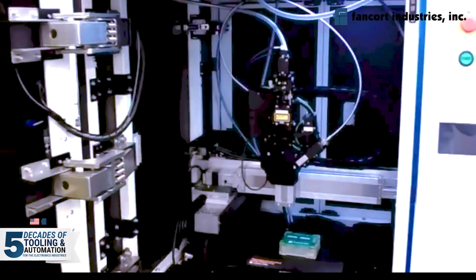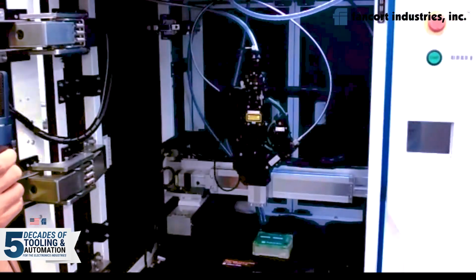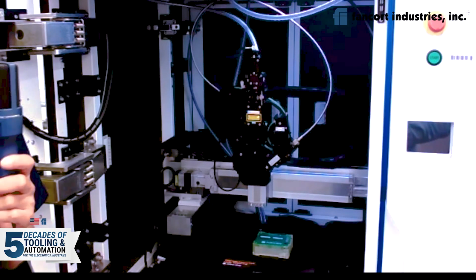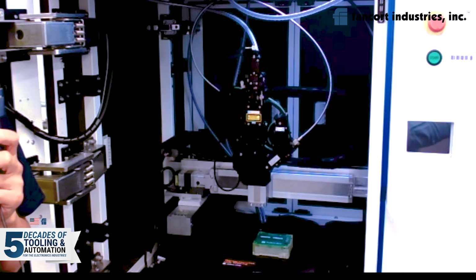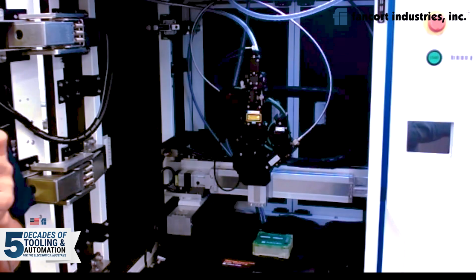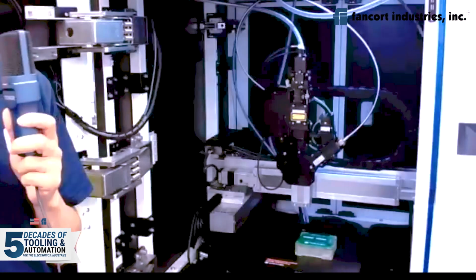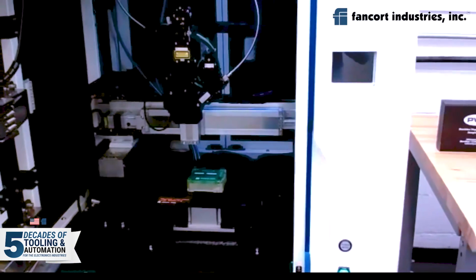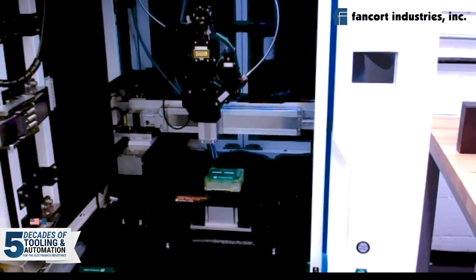The difference between the area laser and the regular laser is that the regular laser focuses all the energy into one small laser spot to solder point by point. Compared to the regular laser, the area laser can diffuse all the energy to spread over a large area. Then you can solder multiple points in that area at one time.